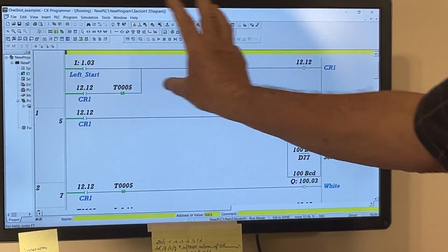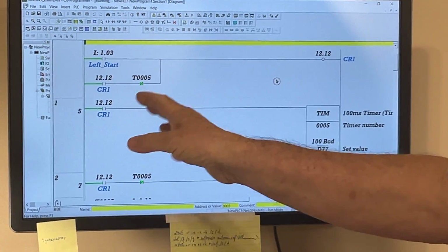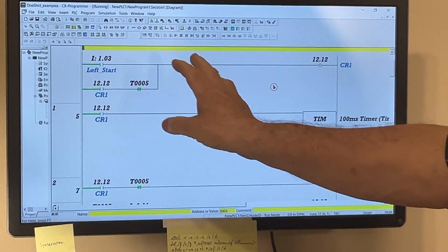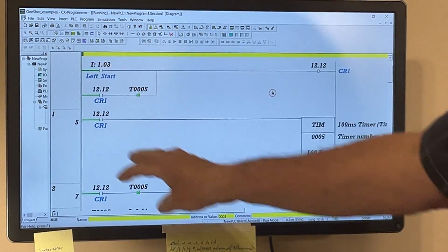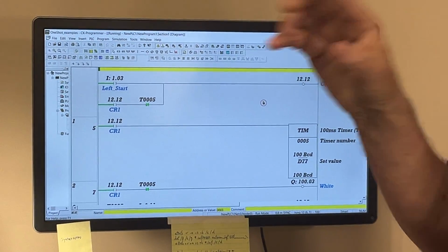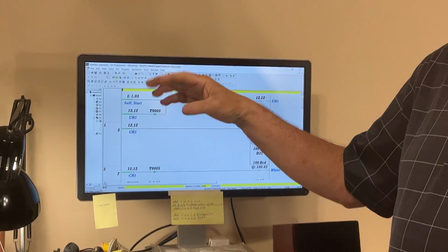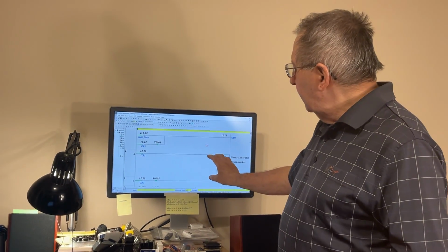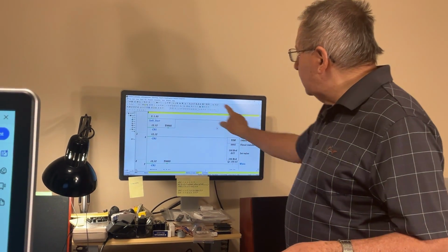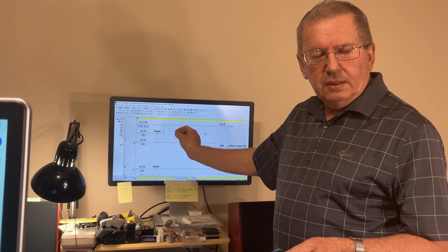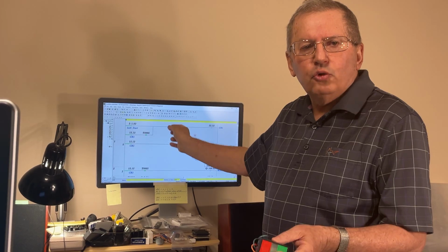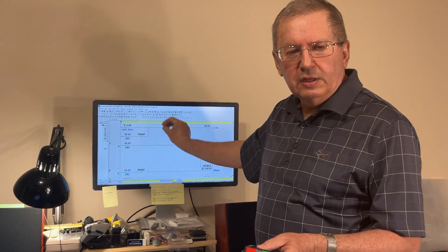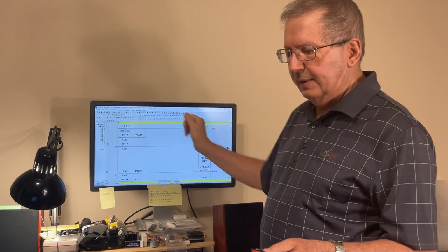And if you just change the addresses here according to the model of the PLC you have, and it's not only about the brand, because I'm using an Omron here, but even for the same brand, if you change the model of the PLC, you have to change addresses here and there, they won't be the same. But the diagram is going to remain practically identical, because this is a classical diagram to make what? To make a monostable circuit in programming with a PLC. In ladder logic, by the way, okay?